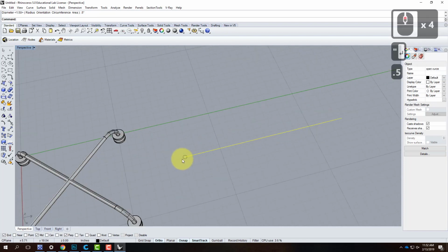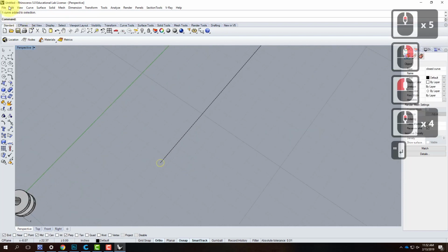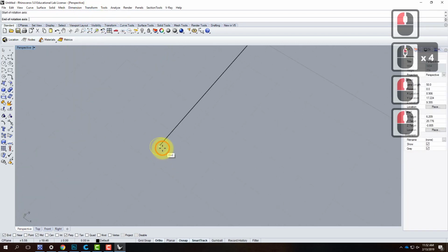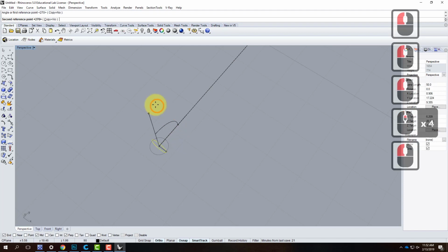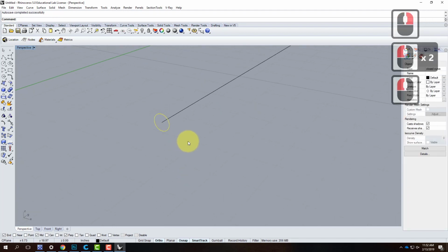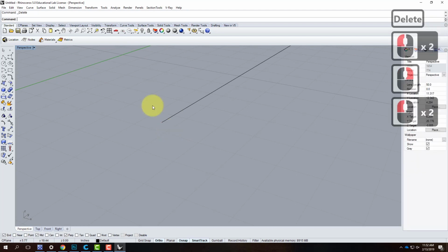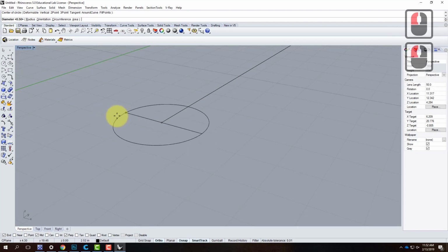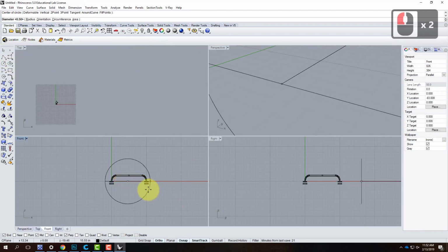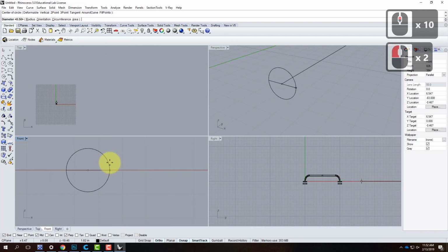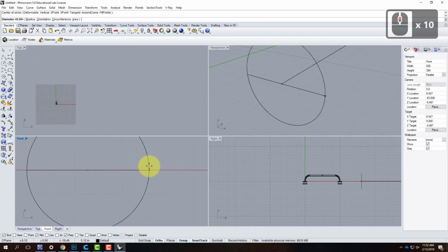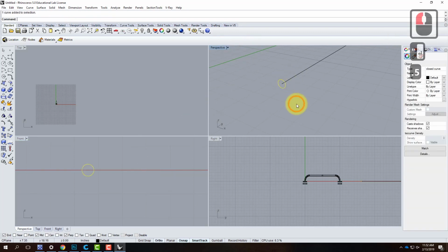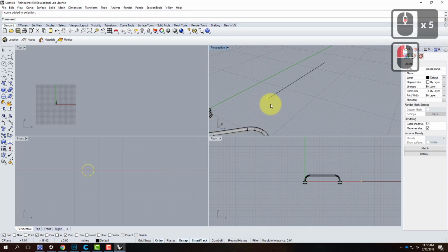There it is. I need to rotate this into the third dimension, so I'll do rotate 3D again. Dimension, transform, rotate 3D. And I'll stand that up like that. Alternatively, by the way, I wouldn't have to go into that if I use the other views. So I have this right now, it's set flat on the ground plane, but if I switched my view, say, into the front view, I don't have to do the rotations anymore. See how it's already standing up for me? I could go ahead and just type in 0.5 as long as I'm in the front view, and it would give me my little circle here in the correct orientation.